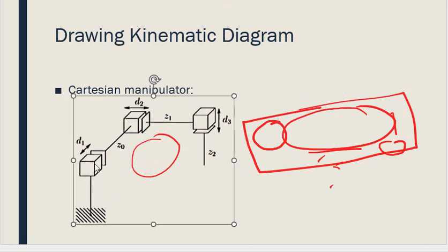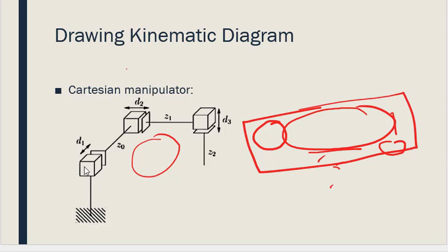This understanding is very important for Cartesian manipulators. And this one is the prismatic joint, where we have denoted Z naught and displacement D naught, D1. Why? Because D is the variable. How much will this arm or limb length increase or decrease?